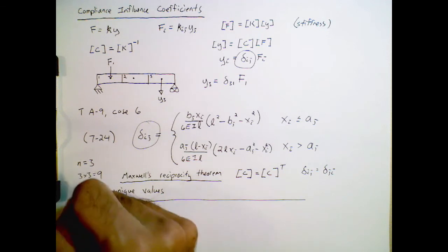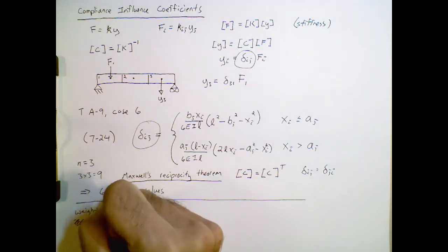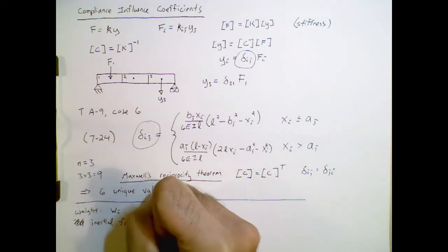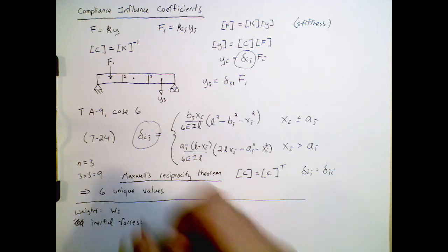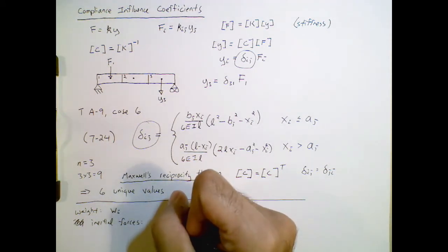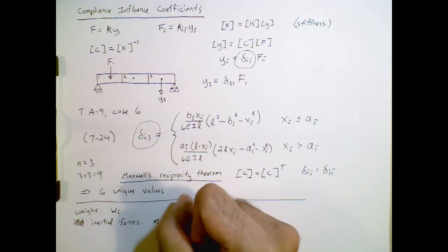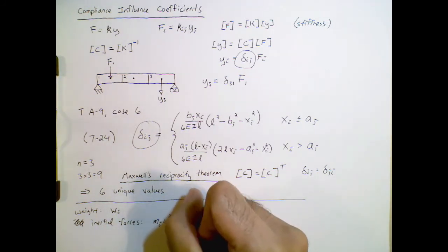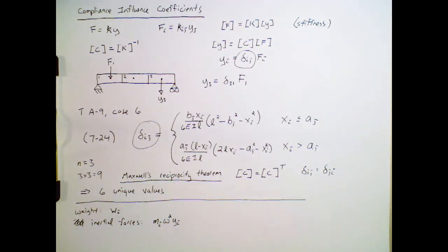And then another important type of load involves inertial forces due to centripetal acceleration. And so those forces, say for a single segment on the shaft, is going to be equal to the mass of that segment times the rotational velocity squared times the transverse deflection of that segment.